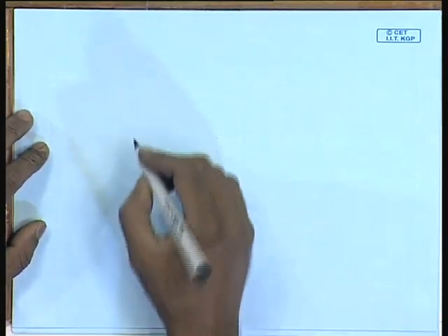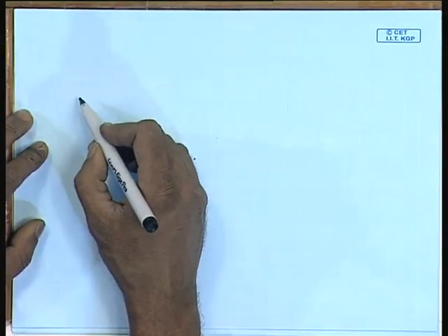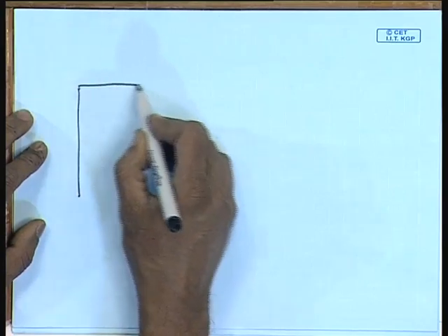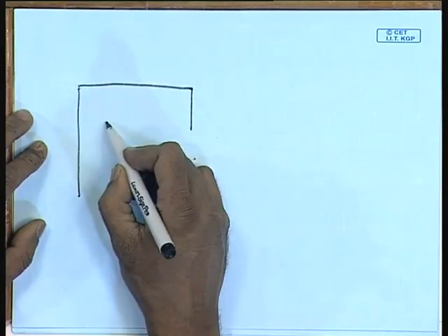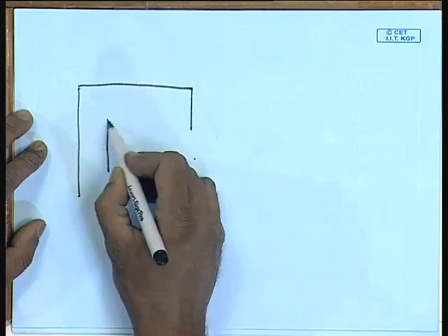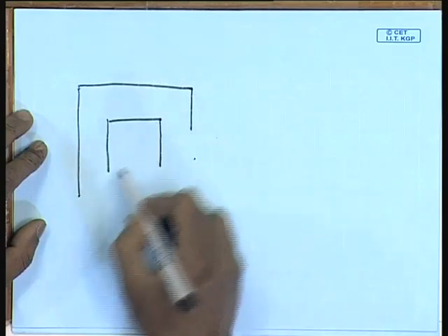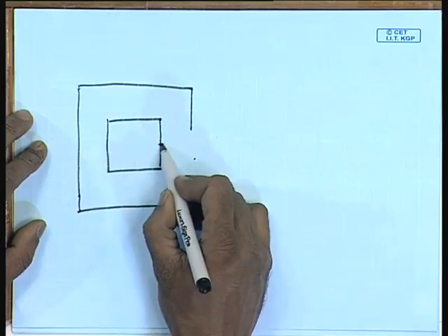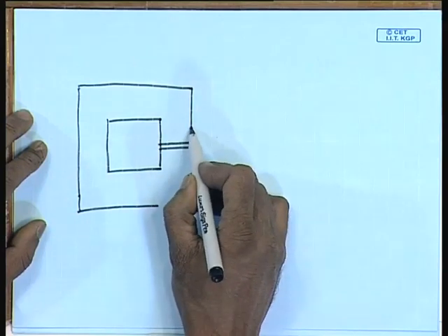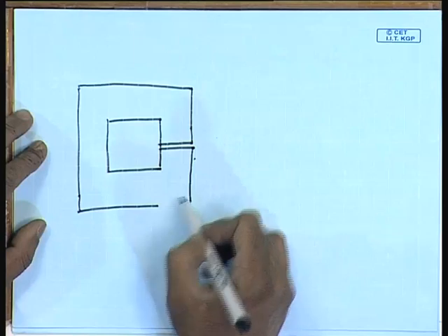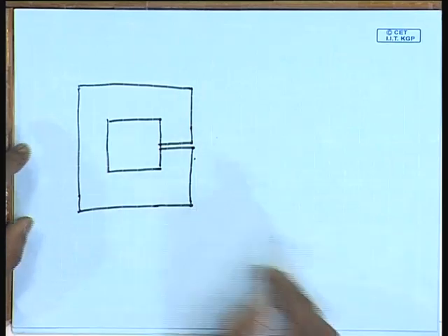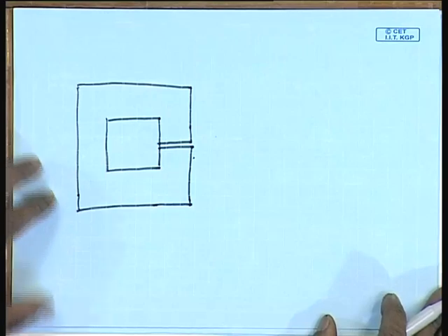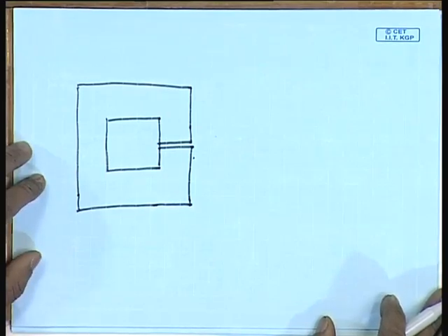A magnetic core need not always be made of a single material. In many cases, a magnetic core, in addition to the ferromagnetic core material, will also possibly include an air gap. Now, the relative permeability of the air gap and the magnetic core are very different.